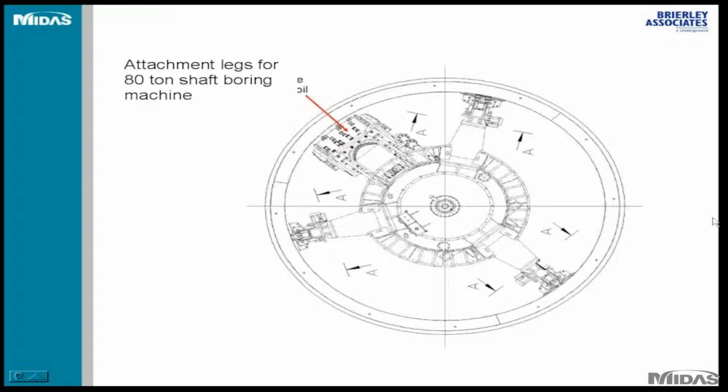Yes, I think I answered this question. One gentleman asked if, in order to account for the TBM breakout, special shaft rings were used. Yes, as I said, in this case you cannot actually change the rings. You use the same rings all the way through. You cannot put 15-inch segments and after that another 20-inch thick segments.